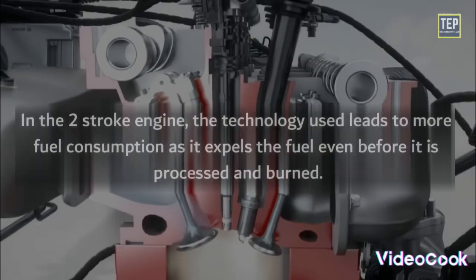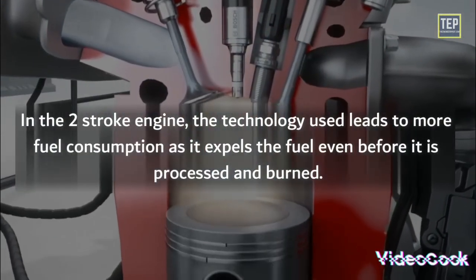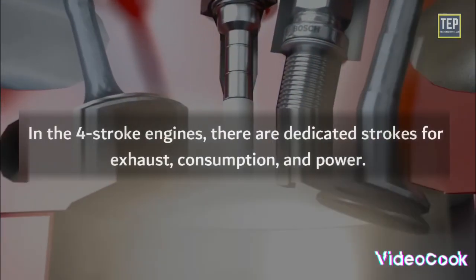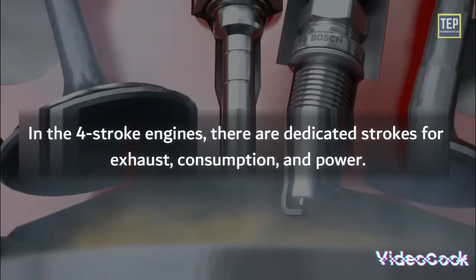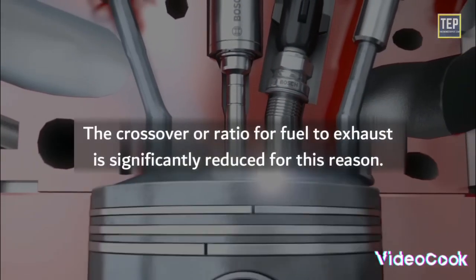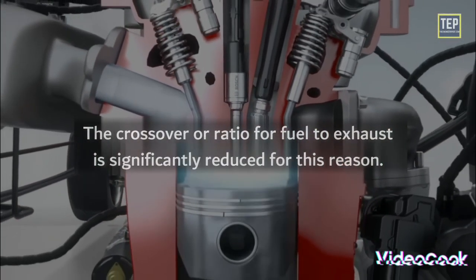In the two-stroke engine, the technology used leads to more fuel consumption as it expels the fuel even before it is processed and burned. In four-stroke engines, there are dedicated strokes for intake, exhaust, compression, and power. The crossover of fuel to exhaust is significantly reduced for this reason.